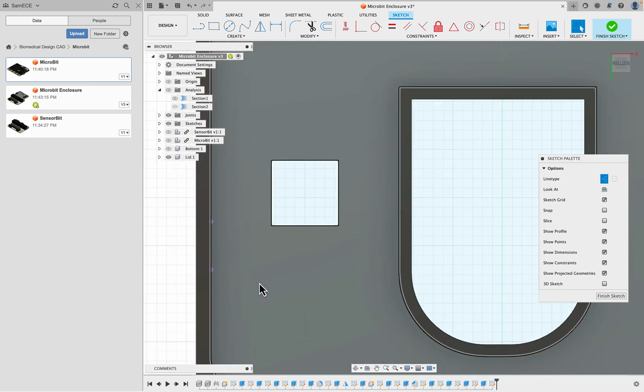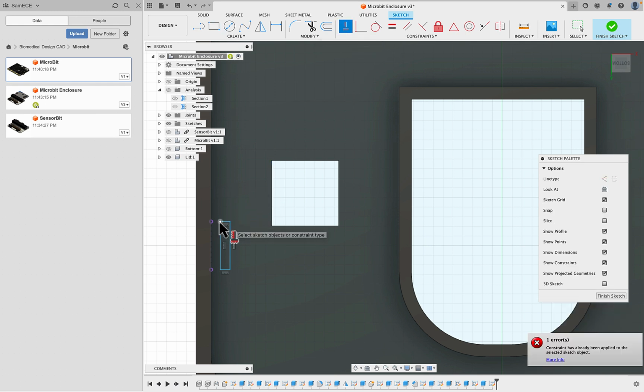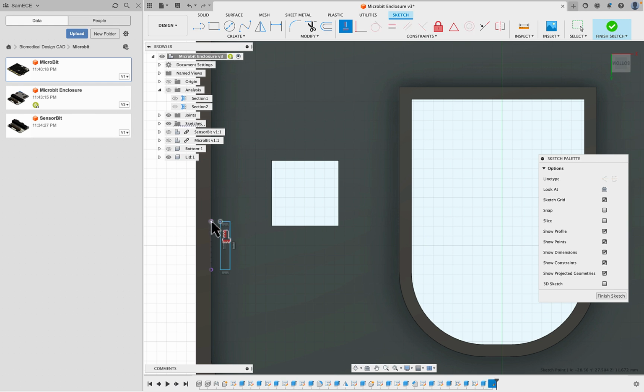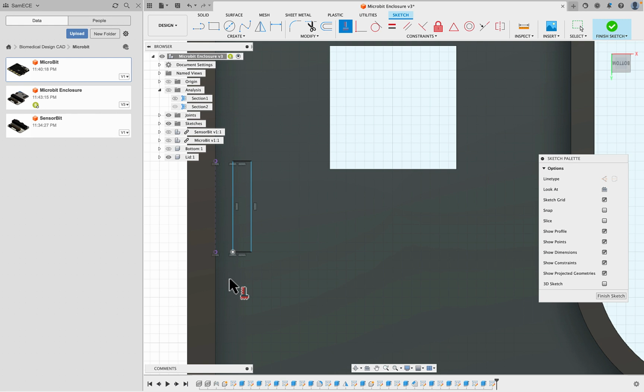So again, I won't create a rectangle going right up to the wall because then I don't have that long lever. So I'll hit R and first off just draw a rectangle, shouldn't be a construction, by freehand. First off, let's ensure that these are aligned. So if I hit horizontal and say this should be horizontal to, sorry, let's do that again. This one should be located horizontally and this one should be located horizontally. So now we are just ensuring that they are placed correctly.